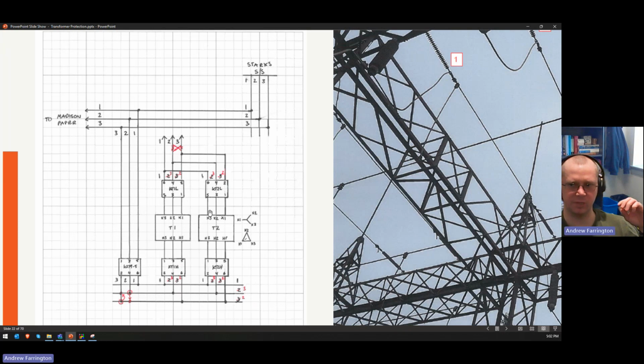because these two transformers paralleled just fine because they had the same phase shift, but they couldn't parallel to this other transformer that was remote to this facility and actually only was tied in some of the time for an emergency backup situation, but they couldn't close it in while both sides were energized because they had the wrong phase shift. So the two 34 kV lines were 60 degrees out of phase, so it didn't work.